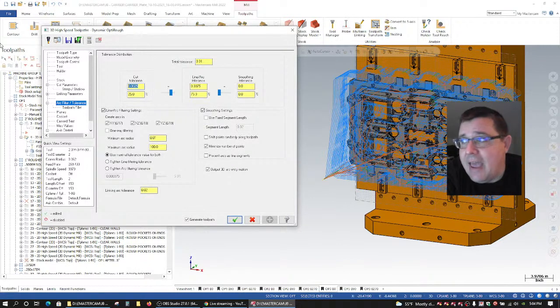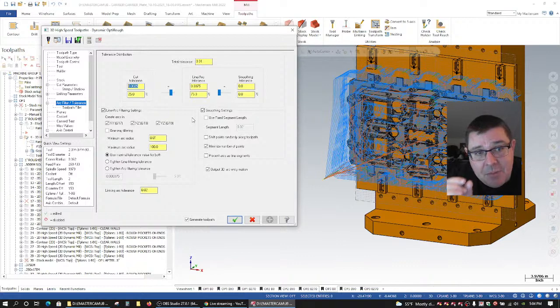And then this cut tolerance is initially used to calculate the toolpath shape going around whatever we're telling it to cut. And then we have this line arc filter that is applied to the geometry. The way this works is, first the line filter flows down the path and sees, within the tolerance that I'm given, are there any small line moves that can be combined or eliminated to give us a smoother path.